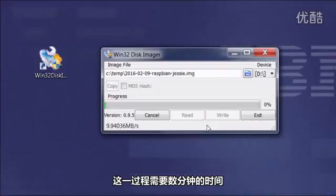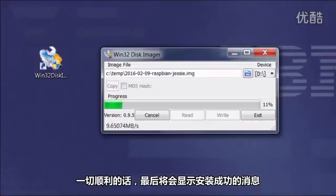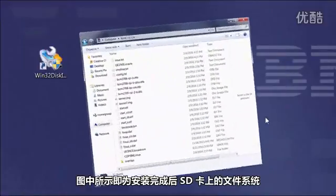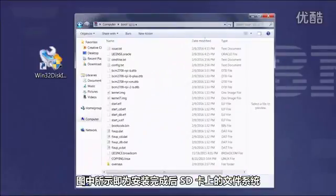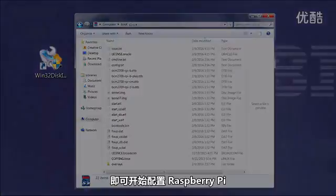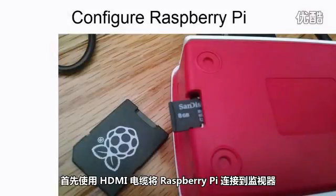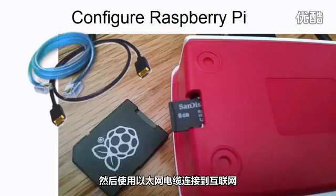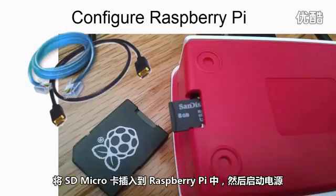This process takes a few minutes, but eventually, if all goes well, a success message is displayed. This is the file system on the SD card once the install is complete. Once the SD card is imaged, you are ready to configure the Raspberry Pi. I connected my Raspberry Pi to the screen using an HDMI cable and to the Internet using an Ethernet cable. Insert the SD card micro in the Raspberry Pi and power it up.